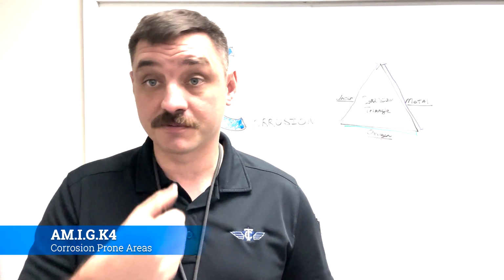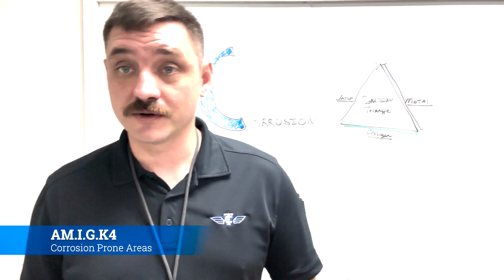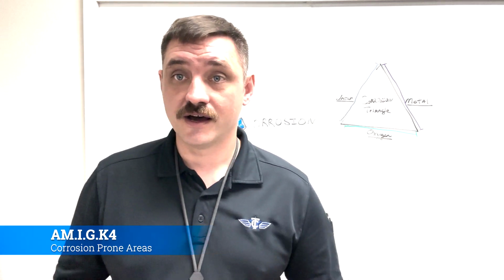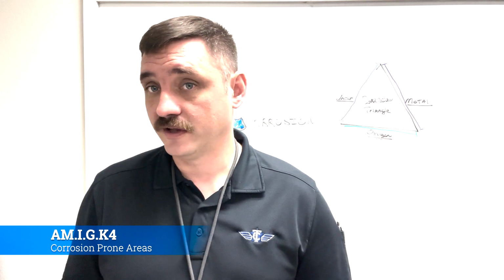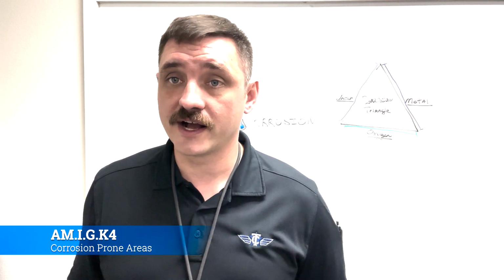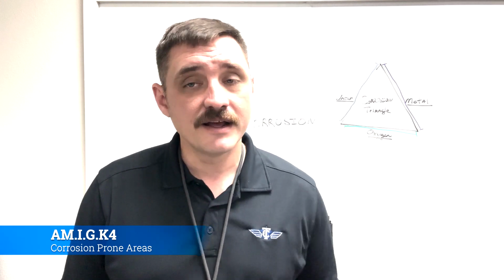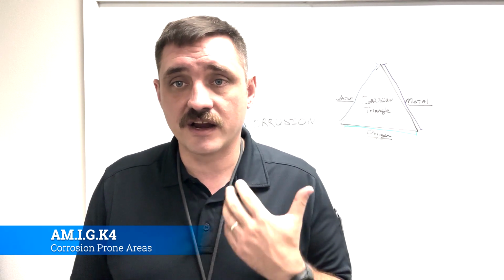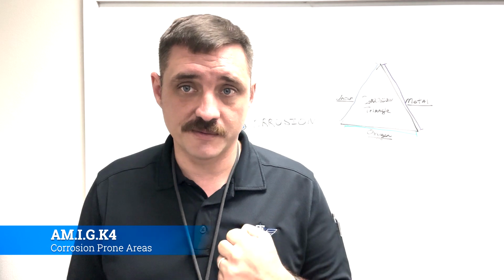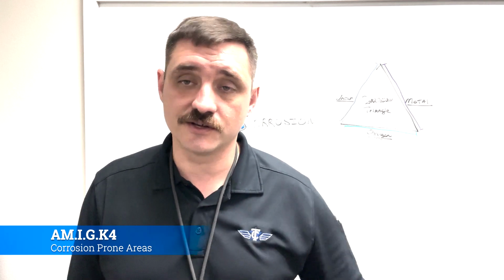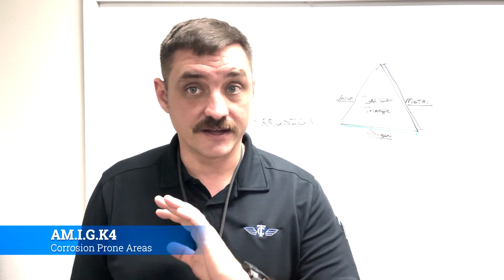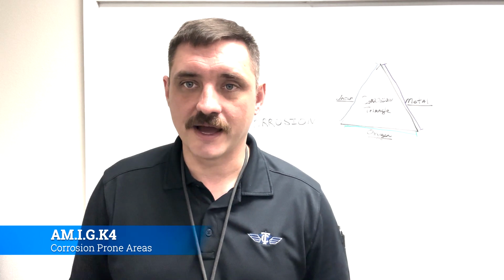I'll tell you, that's probably your number one corrosion find: exhaust pipes, especially on recip engines. They will end up having all kinds of metal oxidation all the way down the pipe all the time. You can think about it, right? It's carrying corrosive elements coming out of the exhaust stroke on the engine, and it's getting all up and down that pipe.